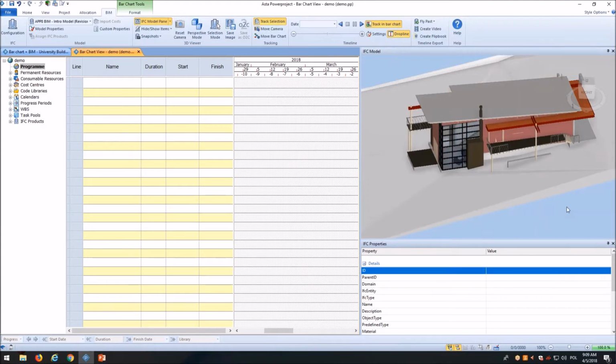If you hold the Shift key and move your mouse from right to left, only those products which are fully in the box are chosen, as you can see now.